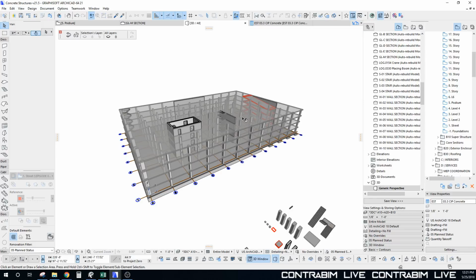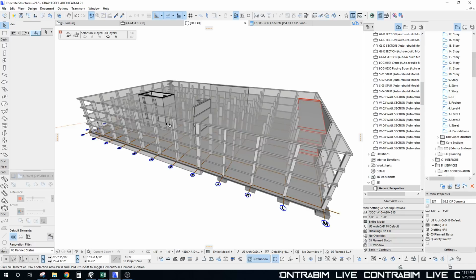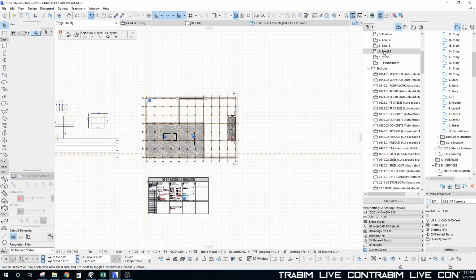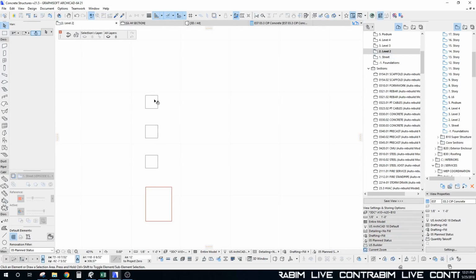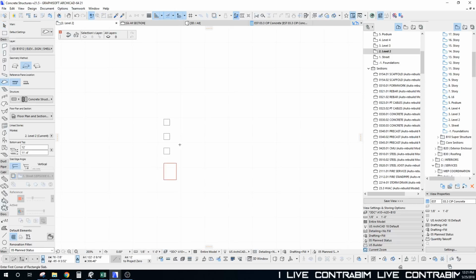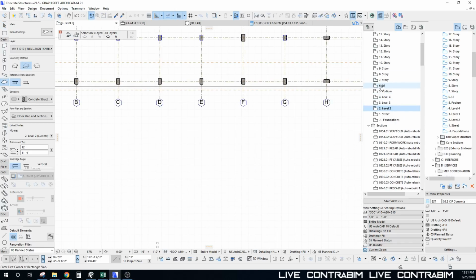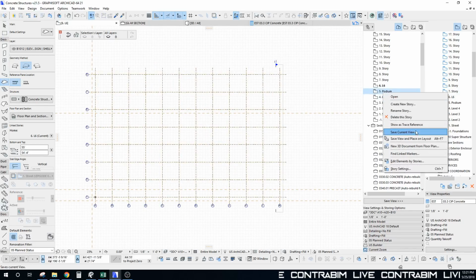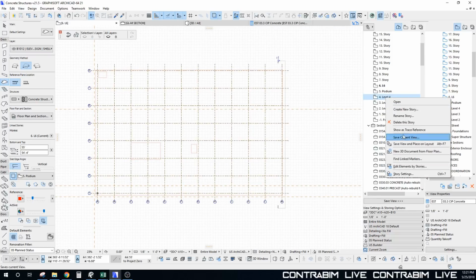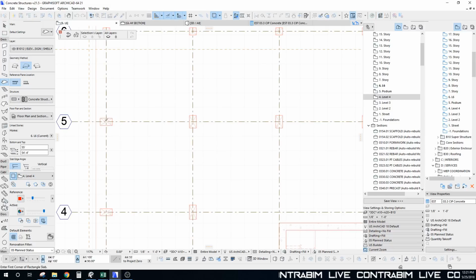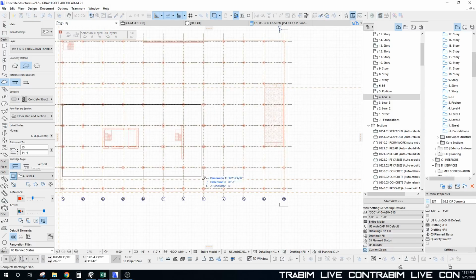All right, so now we're minutes away from copying up the rest of the tower. So let's go ahead and get our shape of our deck in there. And so what I'll do is I'm going to come down to my level 2 because that's where my typical, what I want, an 8-inch deck. So I'm going to pick up that slab, and I'm going to come up now to my level 6 because that's essentially where I'm working from. And I'm going to turn on my podium as a trace reference. Actually, my level 4 is a trace. And so I'm just going to start from, essentially, we'll just go from grid to grid on the shape of our tower.